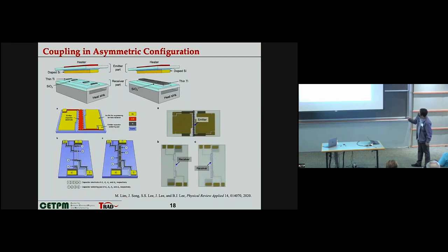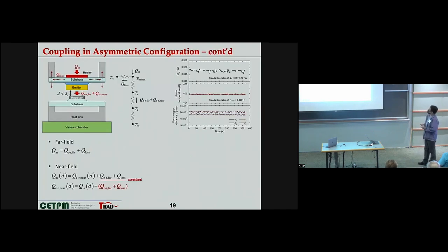And for here, because we have a dielectric receiver, we put a very thin Ti layer, covering about 3% of the heat transfer area as a capacitance pad. And using that, we are monitoring the capacitance just like before. And for these measurements, we also improved our measurement scheme by removing the temperature sensors, because fabricating the temperature sensor was okay, but the heat flux calibration requires the calibration heater underneath the receiver.